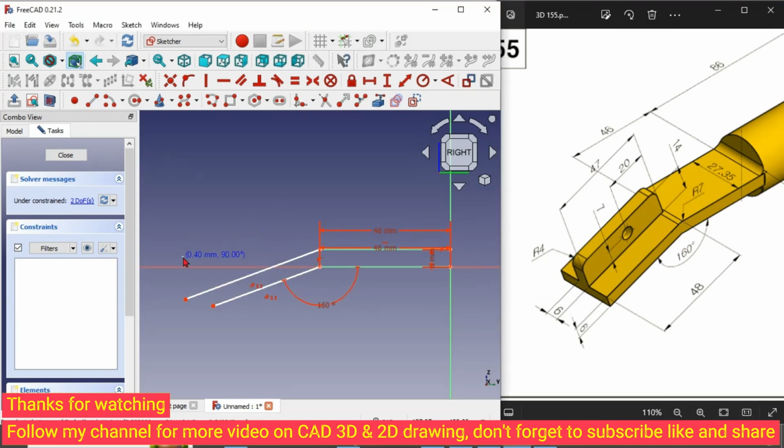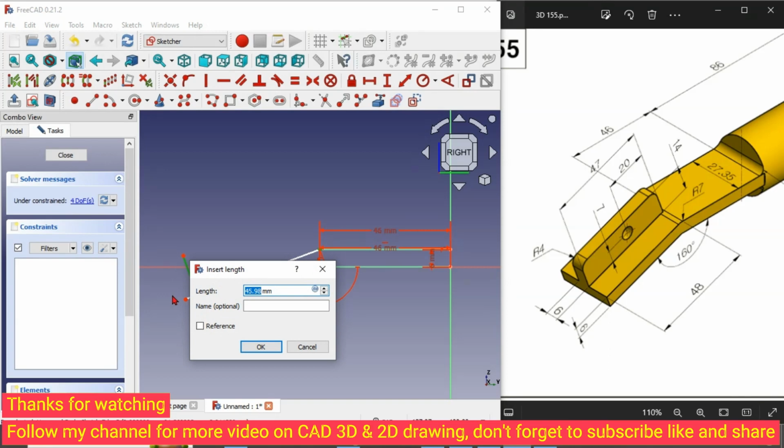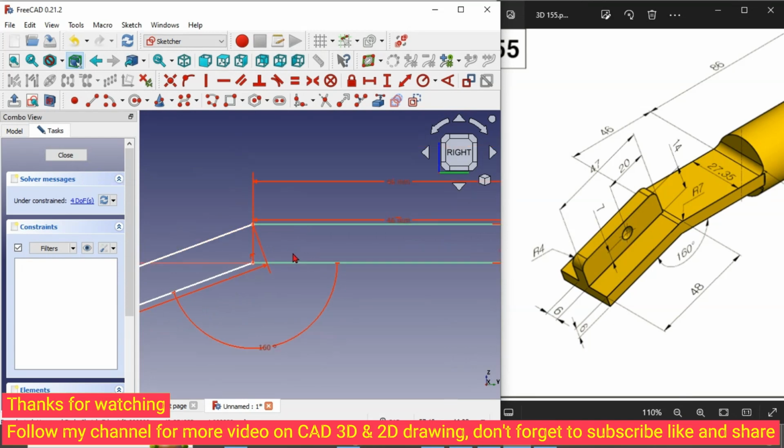And we draw a line here, and we make this line perpendicular to this line, and we set the distance from here to here will be 48. Okay, drag this line a little bit longer. Now we have the basic shape here. Then we have another fillet here, radius 7.